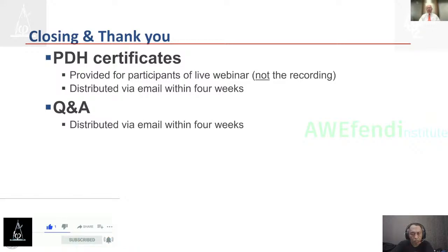So turning this around, the challenge we had was there were a series of irregularities where the implication to design was you're not allowed to do ELF, you have to do modal analysis if you have this irregularity. And the difficulty there is we were requiring people to use the modal analysis method. And when we did those designs, we found that some of those designs with the modal method actually had worse collapse performance than the methods from ELF. So the conservatism of the ELF helped the system out. And it's unlikely that code writers are going to prohibit the use of modal response spectrum analysis, of a more complex form of analysis. But we certainly shouldn't prohibit the simple conservative method.